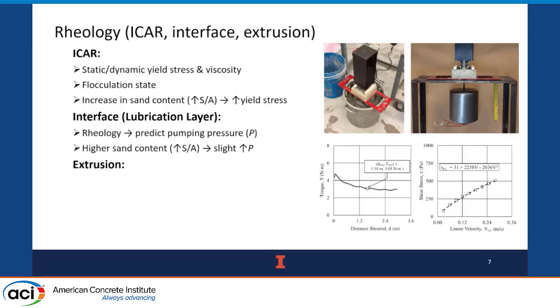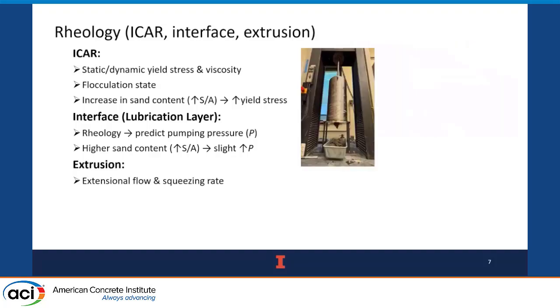Largely affected by paste volume, which I did not change. So it's just affirmation that the gradation has little play in the predicted pumping pressures or the lubrication layer properties. So a slight increase in those predicted pressures with increasing sand content, but insignificant compared to changes in paste volume.